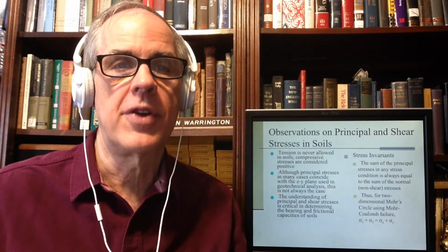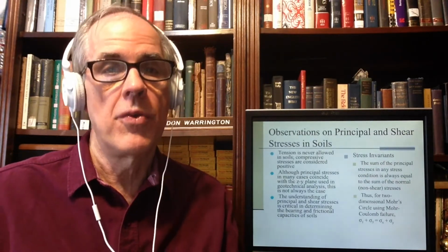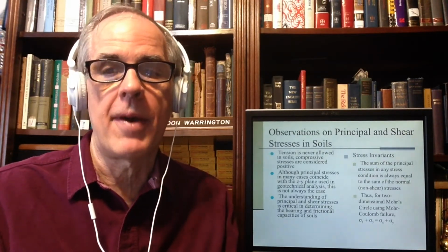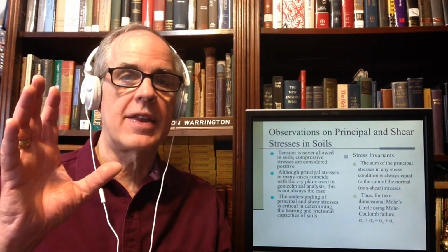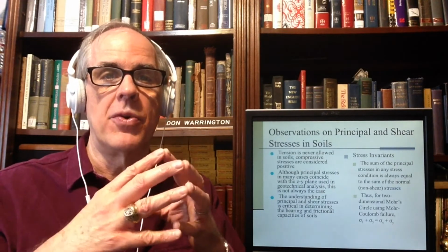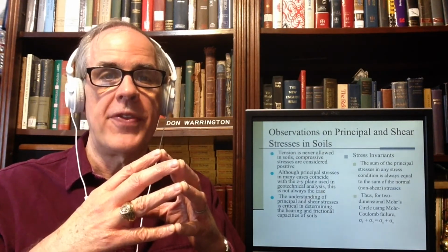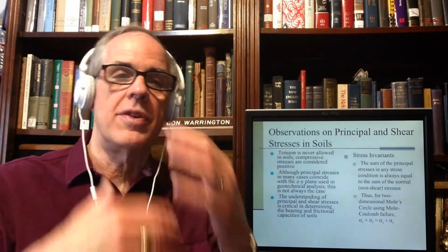There are a few tricks I learned, and one of the most important is the stress invariant. There are more than one stress invariant, but I'm going to talk about one. I mentioned the fact that static equilibrium doesn't care about the coordinates. What that means is that there are some things that don't change, no matter how the coordinates are chosen.